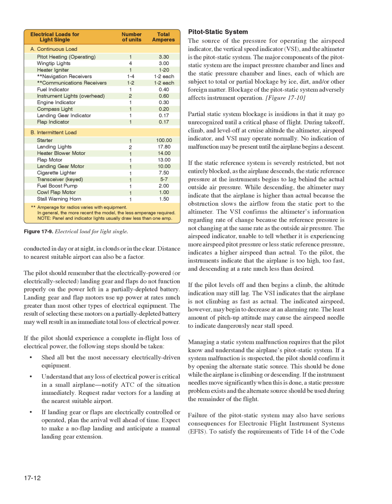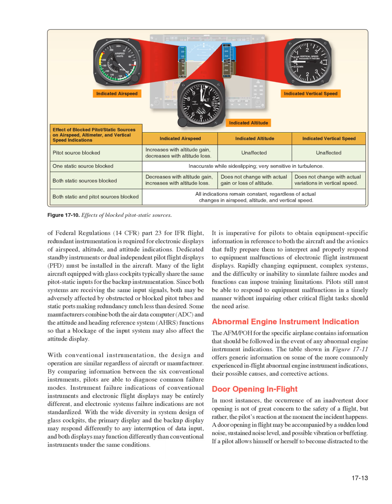Failure of the pitot-static system may also have serious consequences for electronic flight instrument systems, EFIS. To satisfy the requirements of Title 14 of the Code of Federal Regulations, 14 CFR, Part 23 for IFR flight, redundant instrumentation is required for electronic displays of airspeed, altitude, and attitude indications.